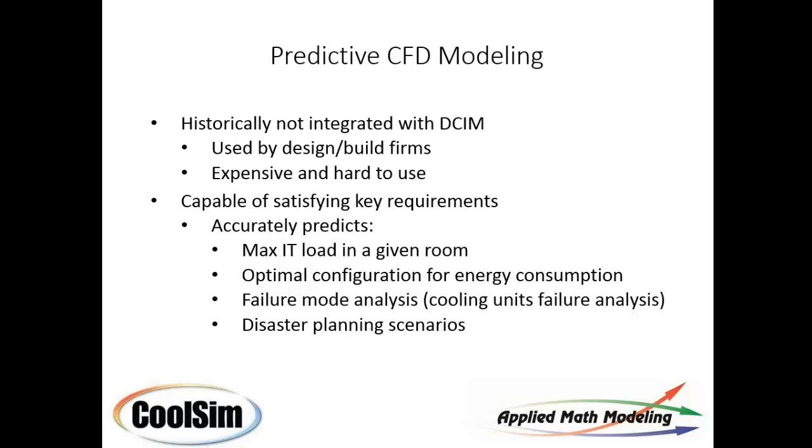But I often go into data centers and measure the amount of energy being consumed by the cooling system and find it equals or sometimes exceeds the amount of energy being consumed by the IT infrastructure, which turns your PUE and your COP, your coefficient of performance, completely upside down. They're both wrong. And it's often because of configuration or poor airflow management or the fact that the site was designed for a megawatt of capacity and is only running 100 kW of capacity.